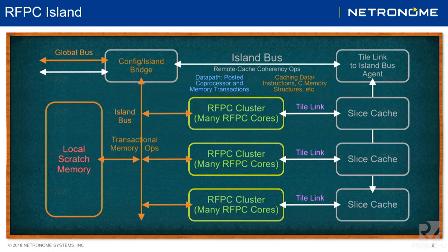The operations are divided into two parts. First, standard data processor type applications that are load, store, and cacheable, which utilize a TileLink protocol and introduce the same level 1, level 2 cache that everybody else is used to, backed with a cache on a memory somewhere else higher in the system. We showed it as the level 3 cache on the previous slide.